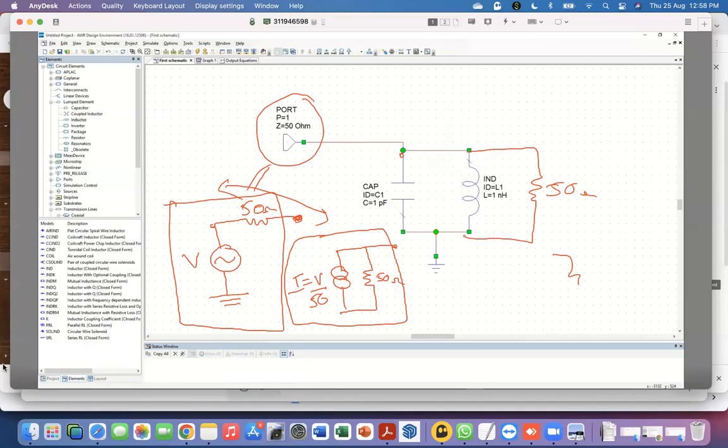So, in the context of optics, this is like putting an anti-reflection coating to make the impedances match so that the reflections are canceled out. This is important because in most of the simplest cases of microwave circuits, you have some source and you want to deliver some power to some load, which is connected via some cable, which is your transmission line. And you don't want the signal to be getting lost in any of this process. So this has to be matched.